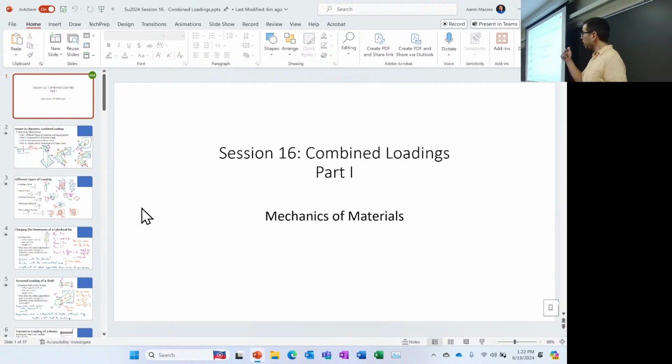Just like the silicones we've talked about, these are thermosets, where they kind of go one way. You heat them up and they cure. With reaction injection molding, you bring in a curing agent and a base and heat it up quickly to get it to cure, but you shoot it into the mold, and when it does that, it becomes bubbly, it reacts, and you try to control that morphology to get a nice